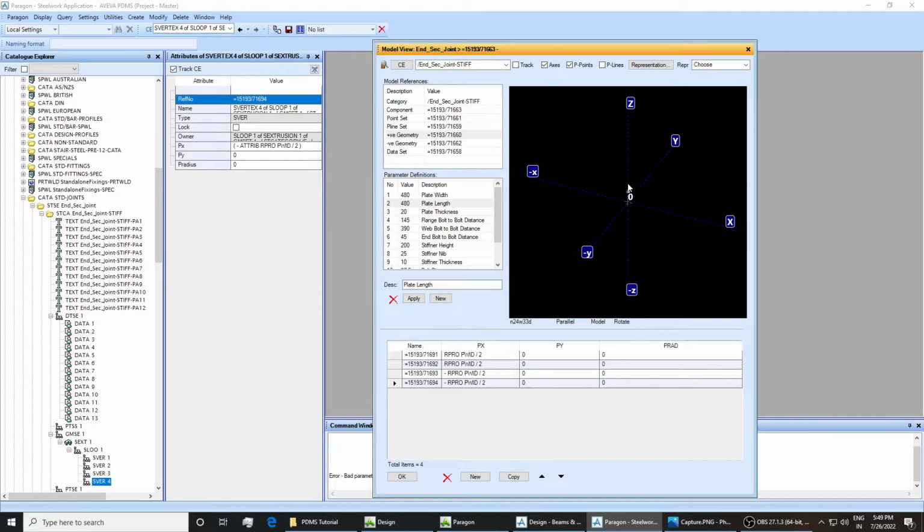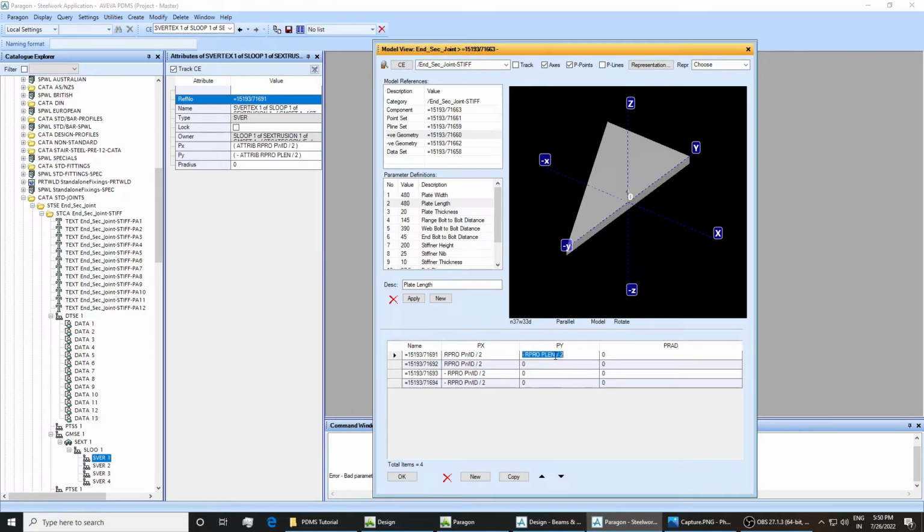So now what do we have to define? We have to define the x variations. Okay. So let us guess, the first value comes in this coordinate, in this zone of this coordinate system, the y and minus x zone. So the first value will be -1. Okay. So we'll just copy it from here and paste it here, and we will change this PWID to PLEN to refer to the length properties. Okay. So I have just copied it here. So the PLEN value has been defined. As I have already mentioned, it will go in the clockwise direction.